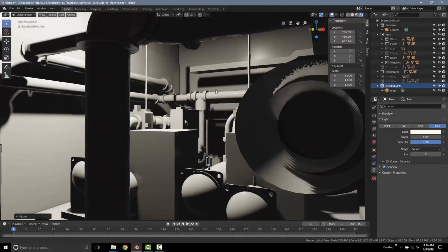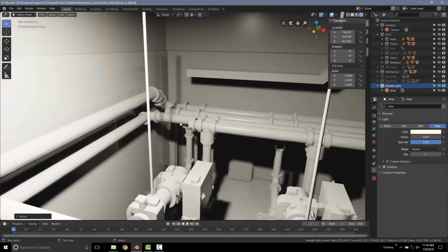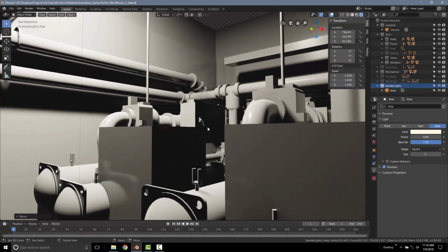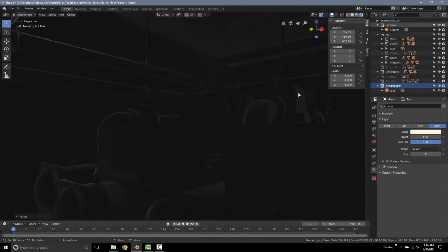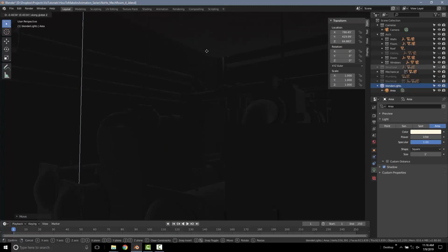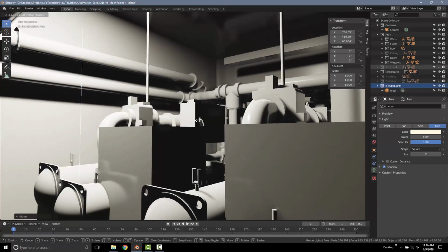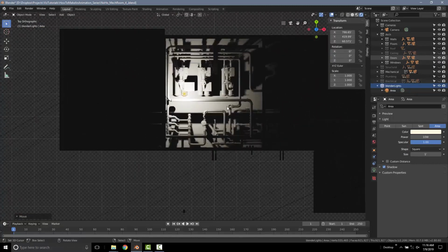As you can see, it looks kind of cool. It's lighting stuff. So actually what I'm going to do is drop in here so that I'm in this space, and I'm going to turn the roof visibility back on. You can see it got dark in here, and that's because the light is above the roof, which is what I was looking for. So I'm going to hit G and then Z and then start moving my cursor down until I start seeing things again. So there it goes. The light just popped back into this space. And then I'm going to turn the roof back off so that I can be in the space.